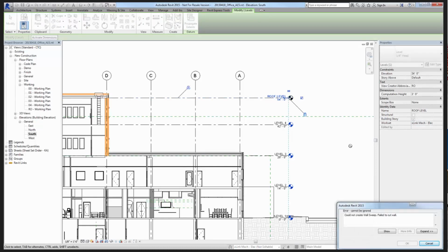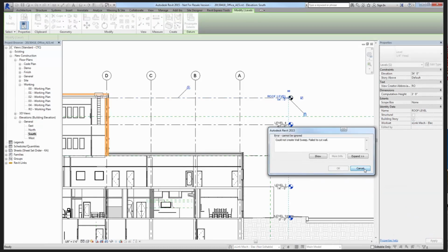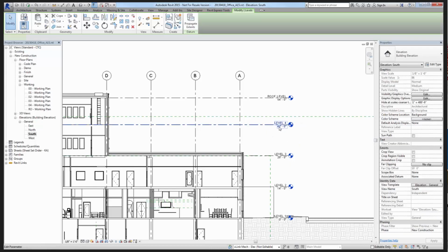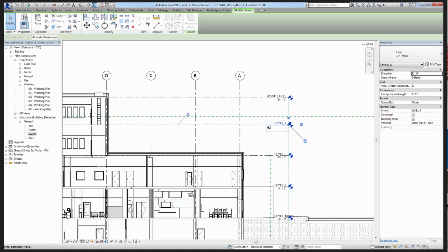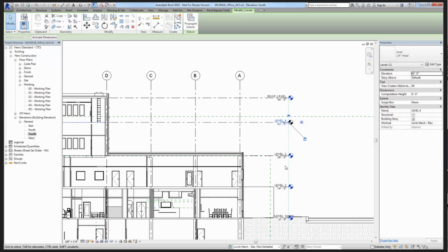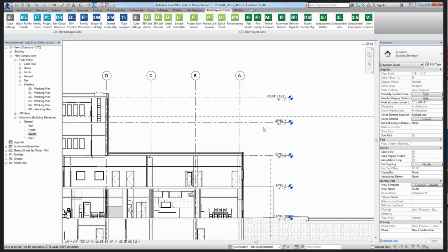It's going to make a couple of revisions here. Obviously, it's going to yell at me about this. All right, I can't do that one. Let's try something else, because for whatever reason, I've got some constraints on the wall that made it angry. Let's take level 4 here and move it up a little bit. Let's go 43 feet. See if this will be happy. Hopefully there are no other crazy constraints that are going to cause me some issues here. Let's see. And go. Okay, I'm going to delete the elements here that I couldn't create the sweep on. I don't care about that for the wall right now. Not super critical. So I've modified this level by 1 foot.